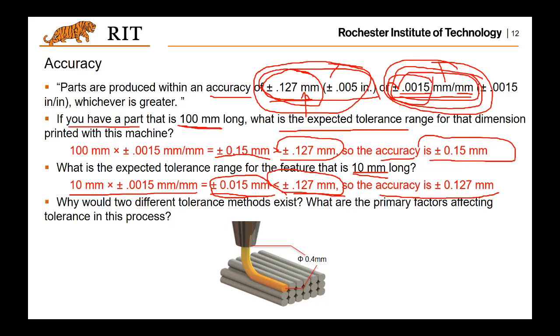the error is 0.0015 millimeter. Because for the plastic part, thermoplastic part, you always have the thermal expansion and shrinkage before and after, during the process. And that will introduce the error. And that error is dependent on the dimension of the part. So that's why we have error like this. In principle, the larger the part is, the larger the error will become. You get it?